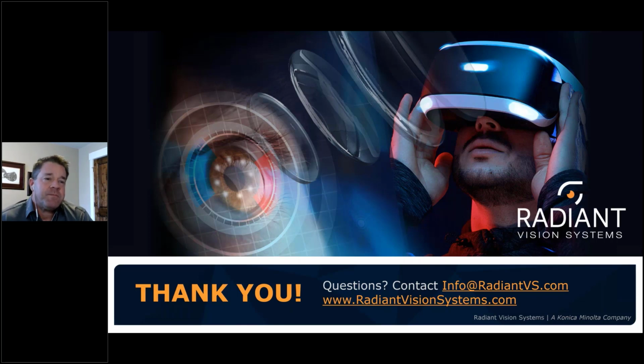How many imaging pixels are recommended to measure a single display pixel? Okay. So also kind of a depends answer. It depends on what we want to measure. But as an example, let's say we want to do correction coefficients, something like a Demura. Ideally, in a perfect world, we'd like to have 9 camera pixels, so 9 of our colorimeter or photometer pixels to 1 display pixel. That's ideal. Now, that doesn't always happen, right? Lots of times we maybe only get a 2x2 array, so 4 of our pixels, something like this.